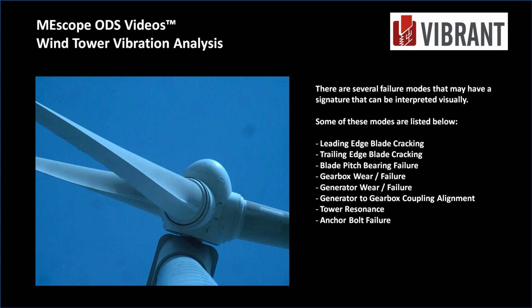It's a big piece of metal, and some of the badly behaving wind turbines out there will crack that ring. And I thought I saw something that might lead to that as a diagnostic, and we'll check that in a few minutes here. There's gearbox wear and failure and generator wear and failure. You can't get those unless you go up in the nacelle, and we weren't allowed to do that. You can't go up there while it's operating. They don't care to insure things like that.